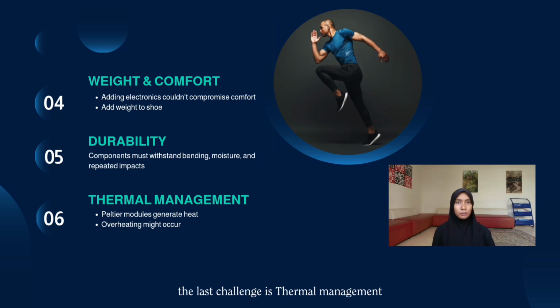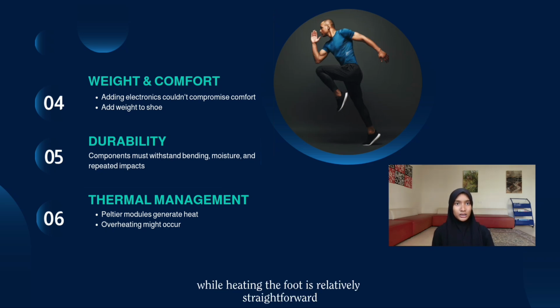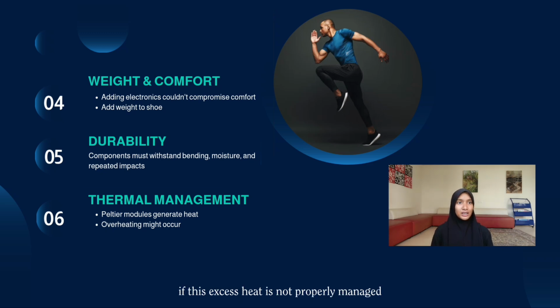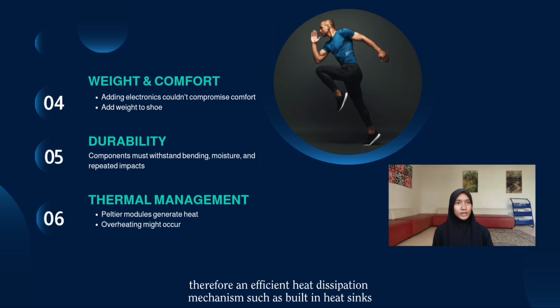The last challenge is thermal management. While heating the foot is relatively straightforward using resistive elements, cooling is more complex. Peltier modules can cool one side but release heat on the other. If this excess heat is not properly managed, it can build up in the sole or battery compartment, leading to user discomfort or component failure. Therefore, an efficient heat dissipation mechanism such as built-in heat sinks, thermal insulation layers, or phase change material must be integrated to ensure safety and performance.